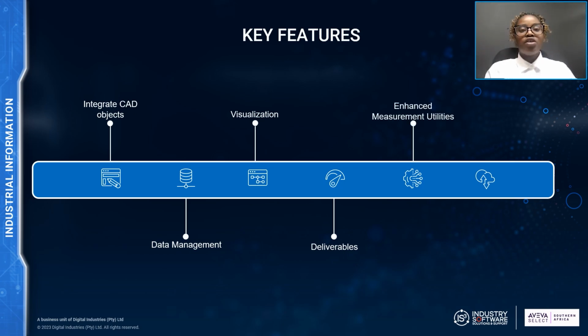AVEVA Point Cloud Manager also offers enhanced measurement utilities. It allows you to semi-automatically measure off as-built structural data. It also allows measurement of pipes and structural members using the point cloud.